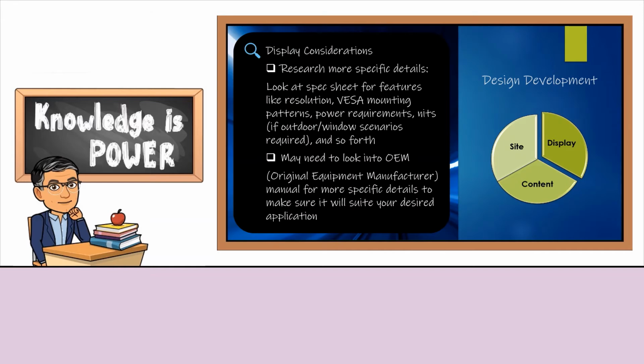Display considerations. Research more specific details. Look at spec sheet for features like resolution, VESA mounting patterns, power requirements, nits in case outdoor window scenarios required, and so forth. May need to look into OEM manual for more specific details to make sure it will suit your desired application.